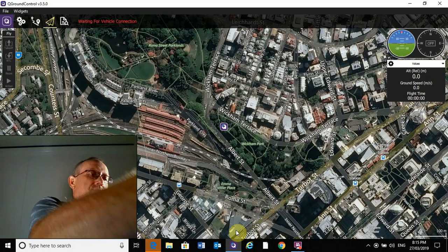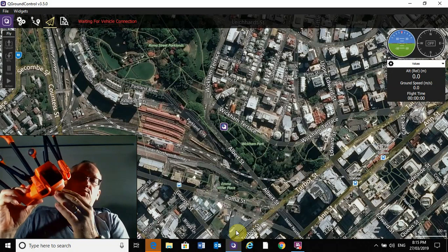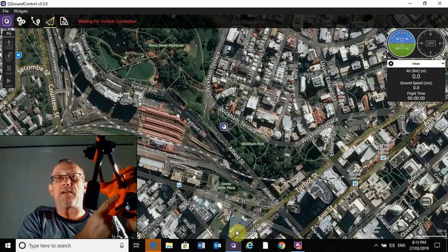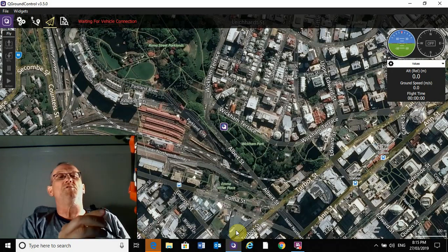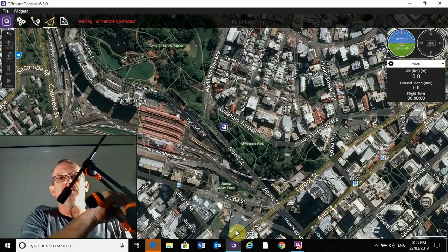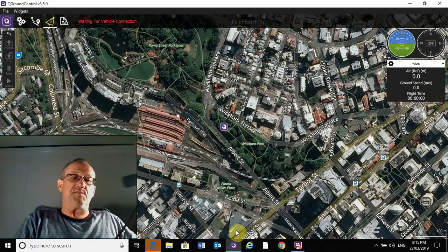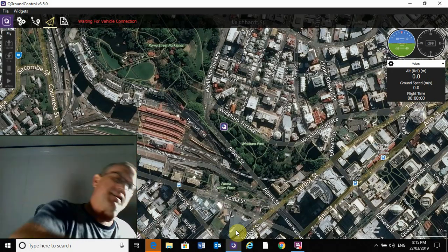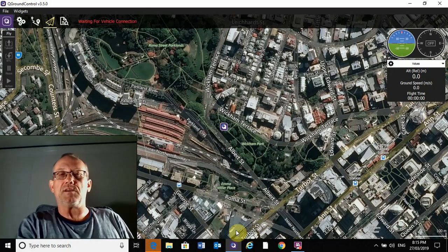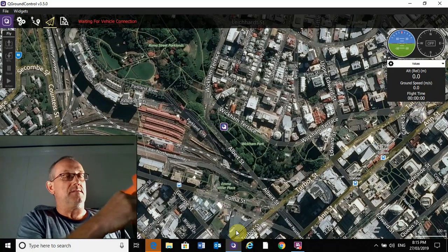Okay, you grab your craft here. You don't have to have a battery in it. What you're looking for is this little port down here in the back right hand corner. So you're going to plug your USB cable into it, making note that the flat surface goes away from the center of the craft, so that the bubble side of the USB goes towards it. Okay, and then once we've done that, plug it in. Now I've already done this before, so I can't actually show you what's going to be found or not found, but you can hear that the vehicle is being found in Windows.